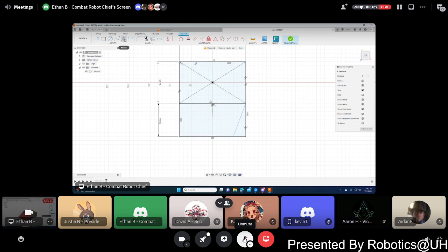So the mirror tool, click mirror, and you click the object that you want to be mirrored. You select mirror line, and you're going to choose that line that I just made, and it creates one that's a perfect reflection of what you did, and it'll apply all the same constraints and properties to it. I'll click enter, and it'll be there. So next, I'm going to dimension this. I'll dimension the one that was mirrored originally just to make it work.